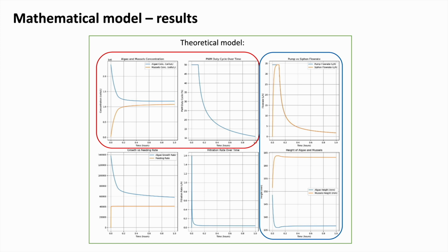After a safety assessment, we decided to limit the PWM duty cycle of the pump to 50%. This limits the developed head to roughly 3 centimeters. In this manner, we are able to avoid bucket overflowing near our exposed electronics.